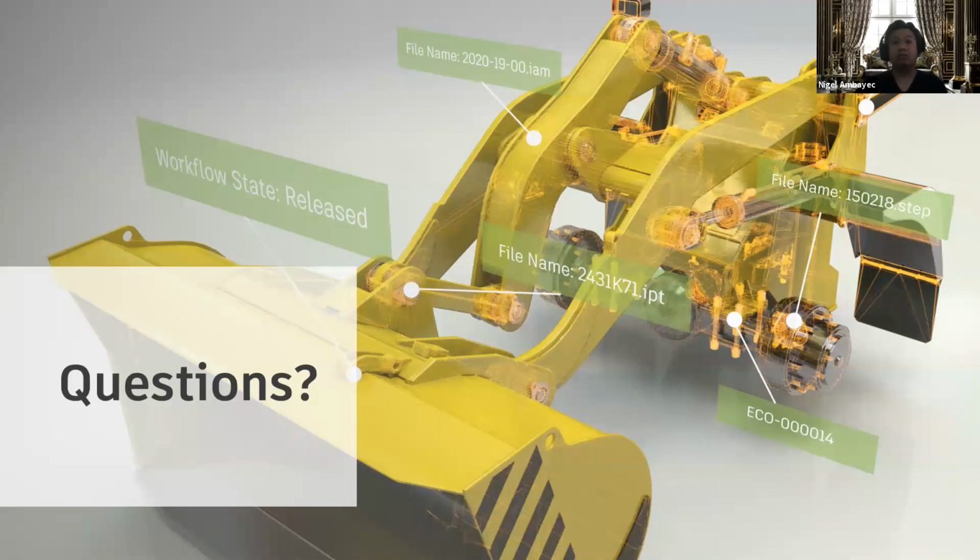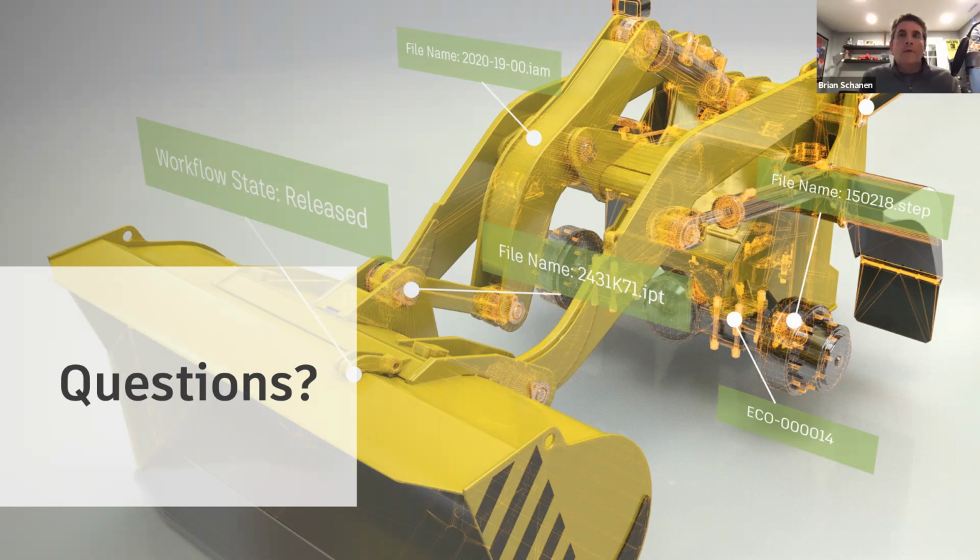So David mentions that Vault Pro has bill of materials by using items, and it's got change orders built in. Is Fusion Lifecycle or Vault PLM an online alternative to make more flexible ECOs, possibly with more cross-platform support? Addressing the items in the item master, Vault Pro is ideal at capturing all of the item information because it understands, take Inventor, assemblies have different types. So you can have normal or purchased or virtual reference. Vault Pro understands that, it's the best at that.